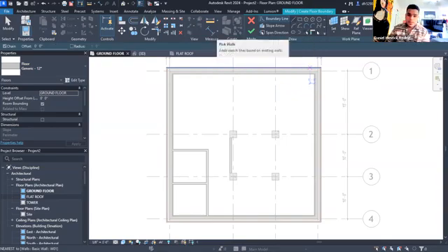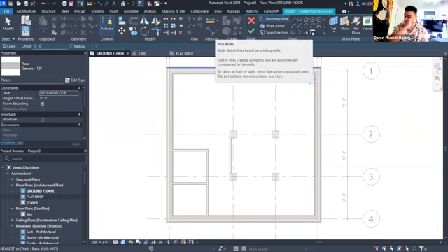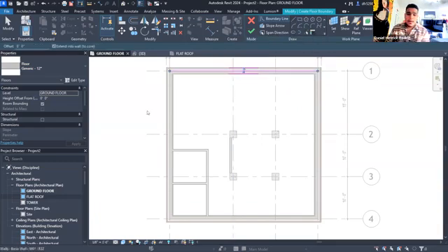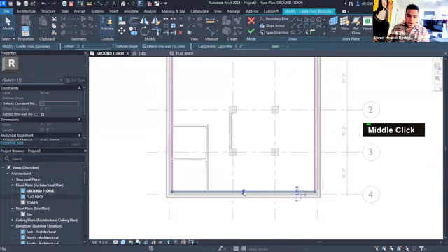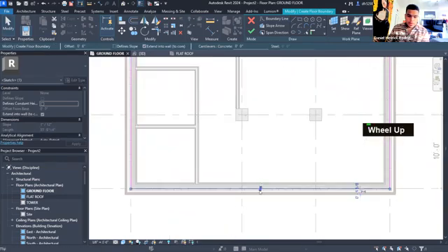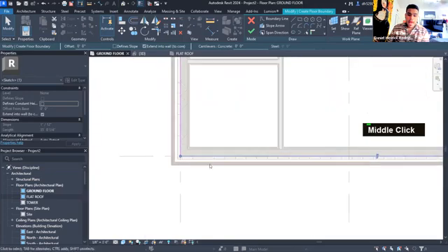These two are the ones that I want you to focus on. They're also self-explanatory, but one is called pick lines and the other is called pick walls, right? So whenever you're creating floors, you're usually just going to click walls, and that's going to allow you to encase your area really easily. You're also able to choose whether you want the wall to be on the inside or the outside. In this case, I want it to be on the outside, but as the drawing shows, it goes to the actual outside of the wall, like all the way to the brick.